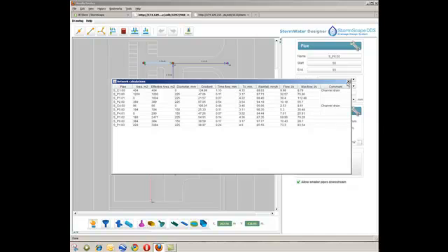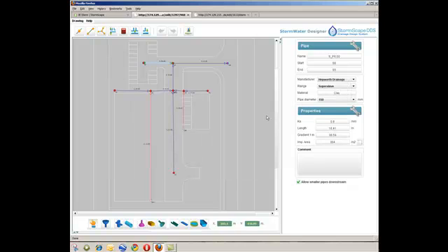At this stage, the user has the option to select the button located next to Network Calculations to perform an auto-design on the network. Auto-design smooths out the gradients along the pipe runs, and the user has the option to select either specific path lengths or the whole of the network.